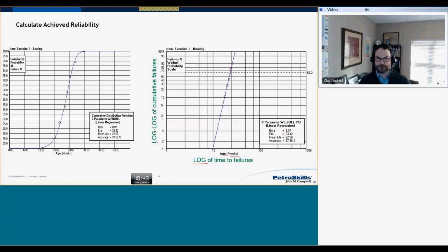To make it work, he did a log of the cumulative failures. Now, the way he did it was rather interesting. Because, again, we've got to figure out what the probability of that failure is. And this is where Weibull really came into his own. But as you can see from this, if I can make this failure mode a straight line, because that is exactly the same data as that. Exactly the same. It's just presented in a different way. All I need here is maybe one, maybe if I've got 2 pieces of data, that's great. That's all I need.